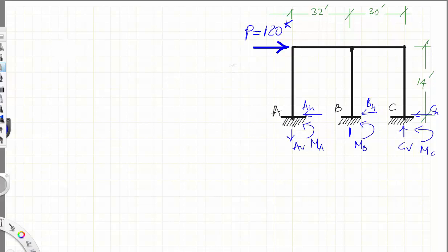So if you look, these are all unknowns. So we need another assumption to be able to solve this problem, and that assumption is that this frame will have an inflection point here, here, here, here, and here. Inflection point means it changes, meaning that this will curve like that and like that. This will be like that and like that. So this is the meaning of inflection, and you can see that in the animation if we want to.